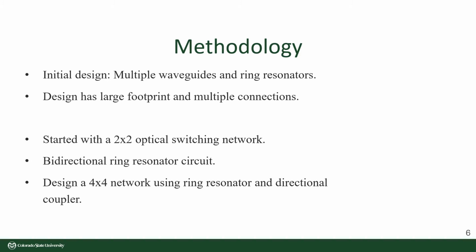But this design has a large footprint and multiple connections, so it was not considered a practical design. Hence, I started with a 2x2 optical switching network by using a bidirectional ring resonator circuit and then expanded it to design a 4x4 network using ring resonator and directional coupler.